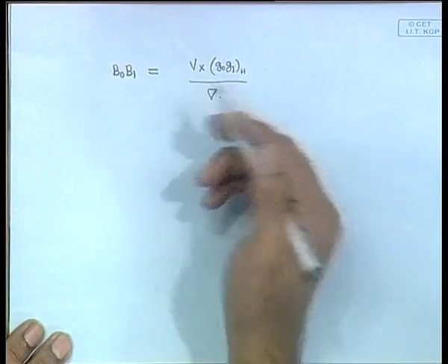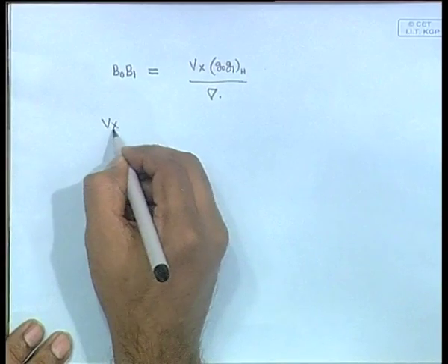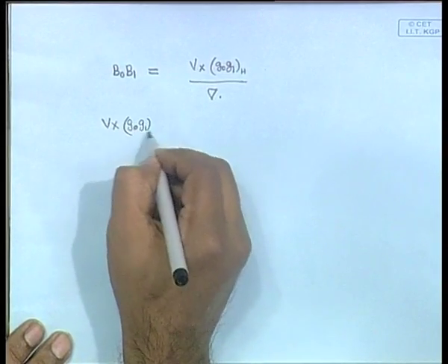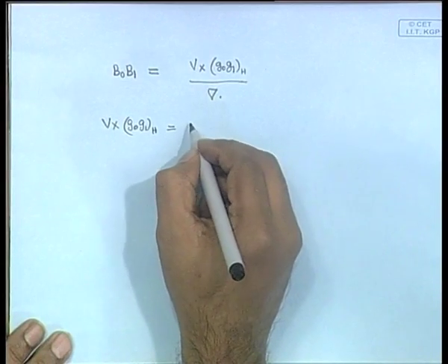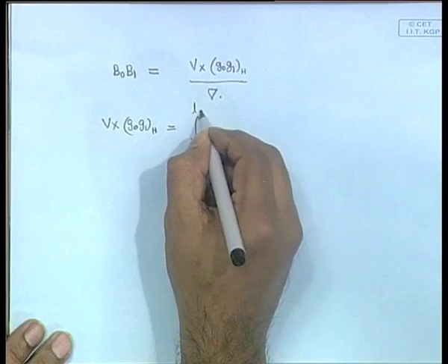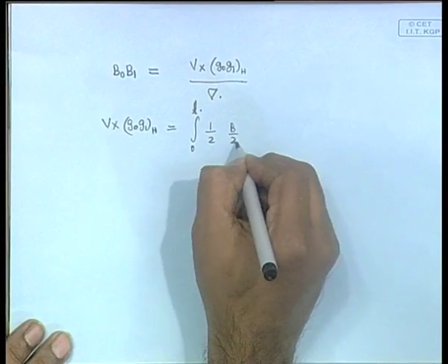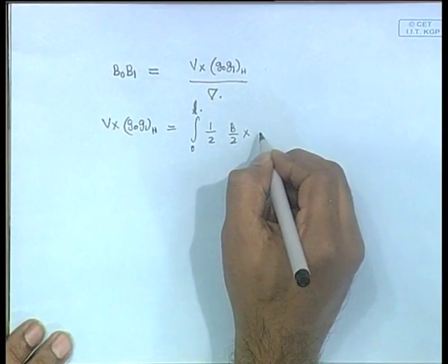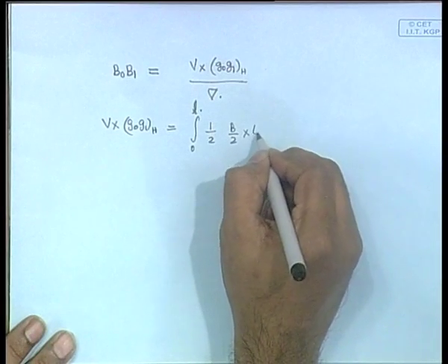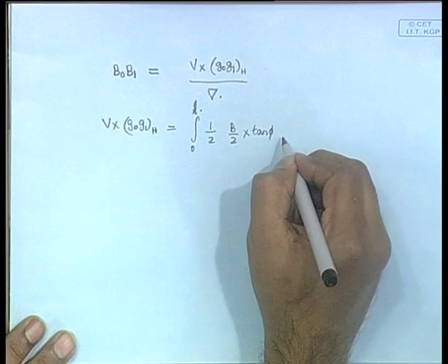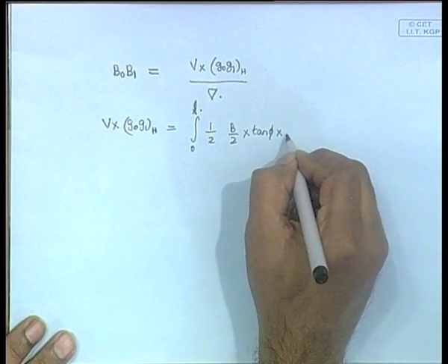Let us consider the first thing alone, which is the horizontal shift. So we are finding B0B1, the total horizontal movement of the whole ship, that is equal to, now this is the volume of the wedge. Now, I will just write this. Remember, it is half base into altitude, then you have to multiply with a dl.